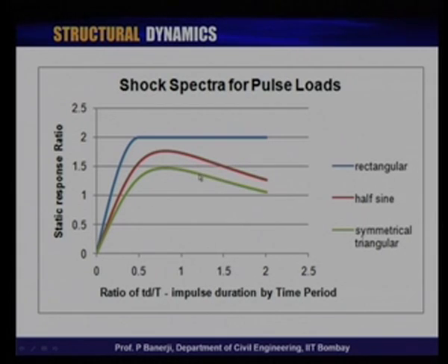If I get the triangle to go really slowly, see, it goes to 1. So, in other words, if Td by t is large, the triangle really goes up slowly, and it tends to 1. All of these points that I have made come out directly from this shock spectrum. And that is the reason why I showed the specific problem that I looked at, the rise time. So, that is a very interesting point of the pulse characteristics.